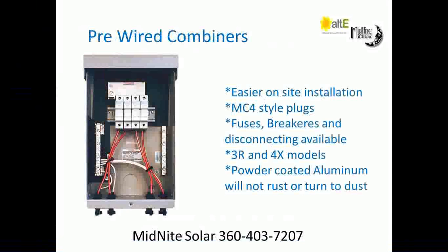We can pre-wire it for fuses or circuit breakers. If it's a combiner box, it will take circuit breakers. We do pre-wire only the MC4 style plugs. We do not pre-wire Tyco. It's just too confusing. There's too many adapters and too much stuff. So we only do MC4. We have models that are NEMA 3R and we have models that are NEMA 4X. And every one of our combiner boxes is powder-coated aluminum, so they will not rust or turn to dust like fiberglass will, say in Arizona or in the desert.